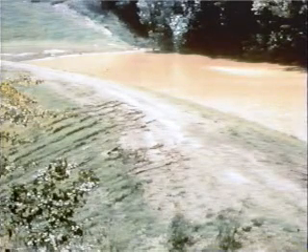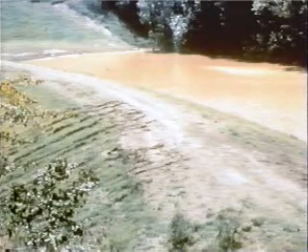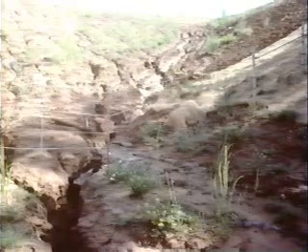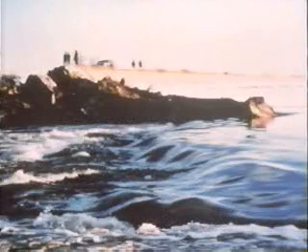One final embankment deficiency to look for as you inspect the dam is surface runoff erosion. If it's not corrected, more serious problems can develop, such as deep erosion gullies on the slopes, both at the groins and in the central portion of the dam. In extreme cases, these gullies can breach the crest. Surface runoff erosion, or for that matter any deficiency, may be caused by conditions or problems unique to a particular location. Always be alert for such conditions in your inspection and include them in your report.